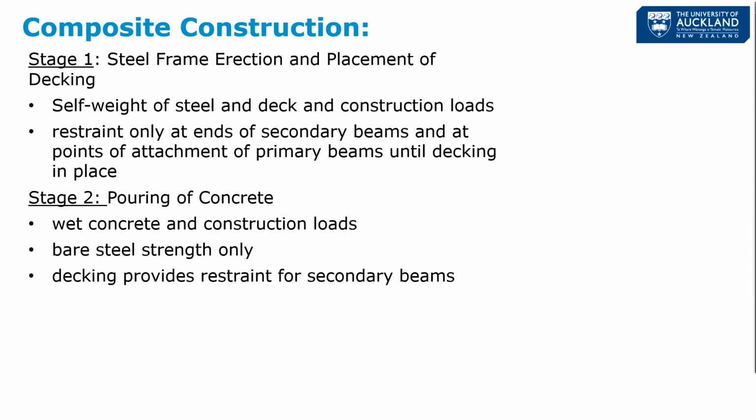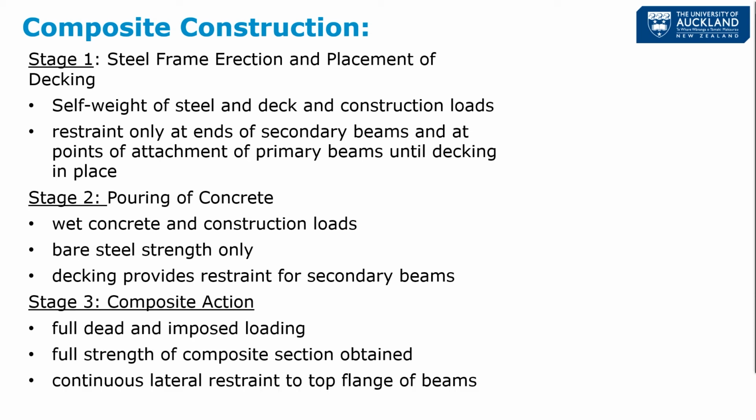So we have to actually design those steel beams, the secondary beams, as beams alone, carrying just the weight of that wet concrete. And it's not until that concrete cures that we can take advantage of that composite action. And then our design case for there would be our full imposed loading on there. And the nice thing is that as that concrete has cured, it provides full lateral restraint to all the beams which it's tied into, both primary and secondary.